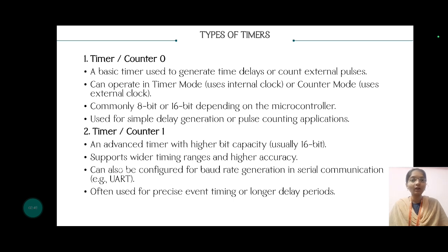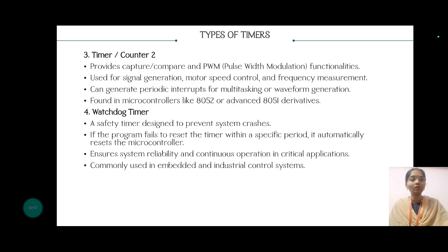And next we have timer or counter 2, which provides extra features such as capture or compare or PWM functionalities. It's used in applications like motor speed control, waveform generation, and frequency measurements.